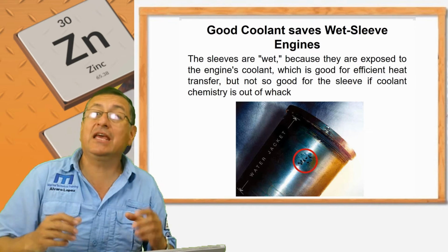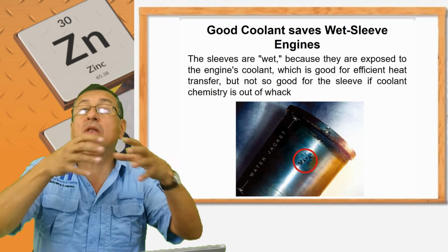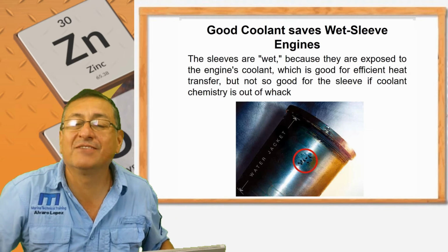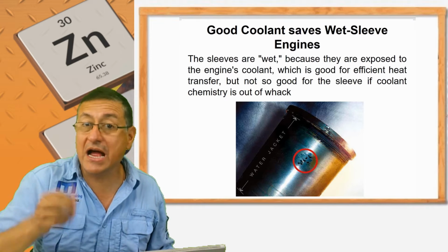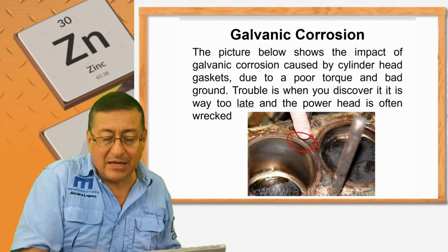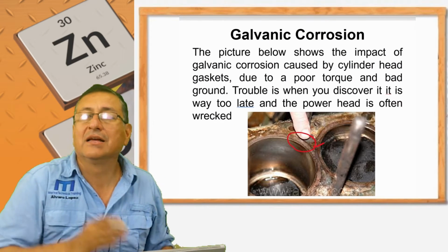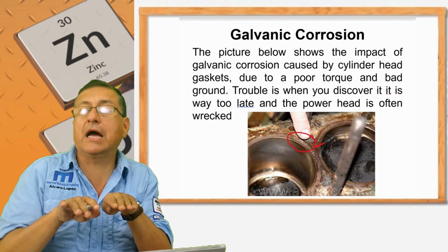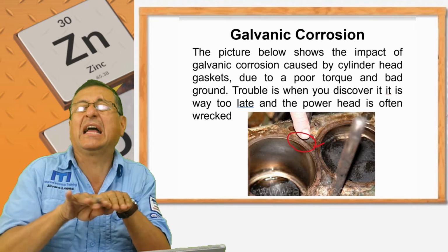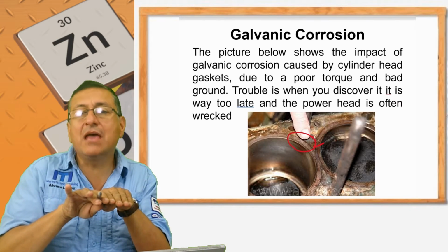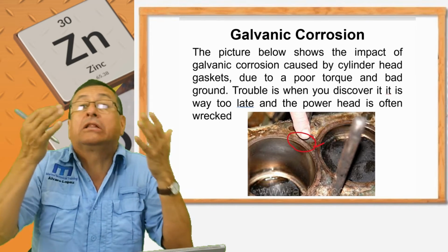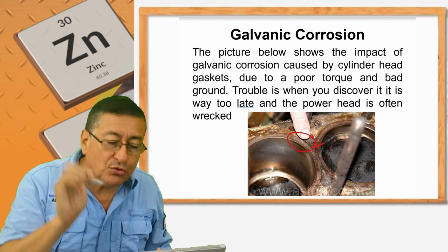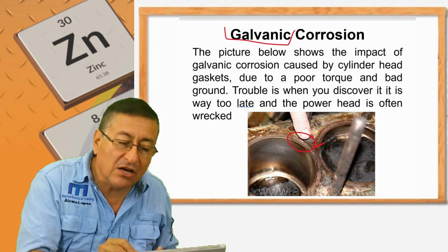And additionally, the block is regular gray iron. You remember? One type of cast iron, gray iron. And here, in between the sleeve, in good steel, high quality, with regular cast iron, in that neighbor you have two dissimilar alloys, and each produces galvanic corrosion.